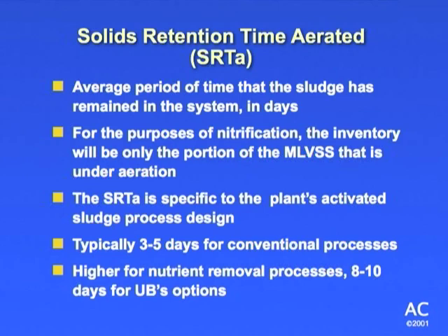Obviously, we've come up with an SRT for this plant, for the 3 different modes, each mode, to get the optimal treatment from that process. But you're going to have some latitude, because once you start operating that mode, you may find it might be a little bit higher or lower, but not horribly higher or lower, okay? Shouldn't be a big difference. The SRT is specific to the plant's activated sludge process design.